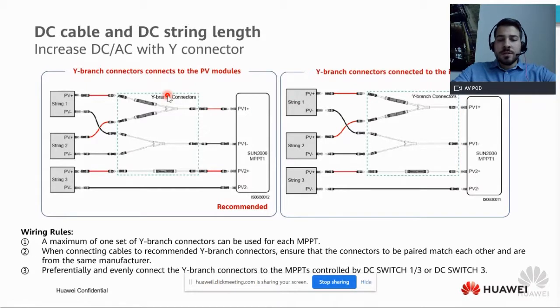This is the reason that the PV panel cannot withstand a short circuit from three strings when there is a problem in one of the strings. But for two strings, the standard makes it possible to not use any fuses. But as I mentioned, for this case, you have to use fuses.